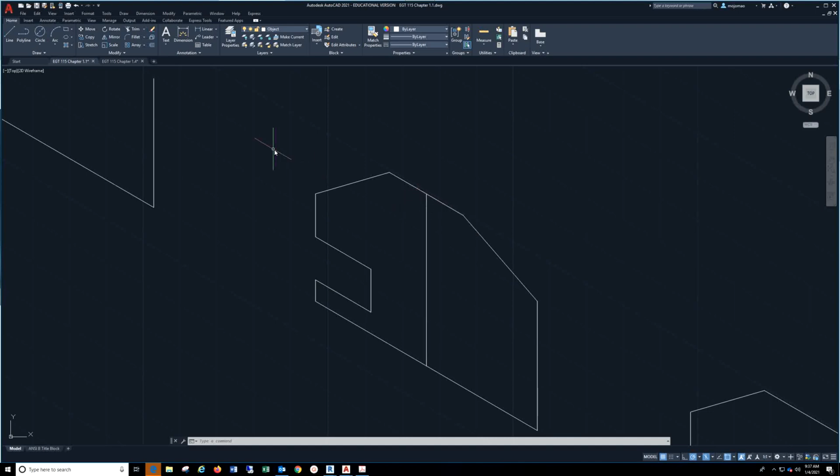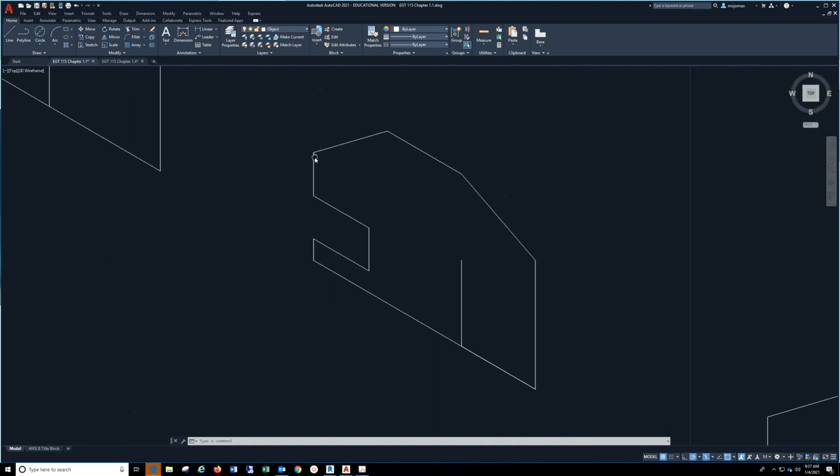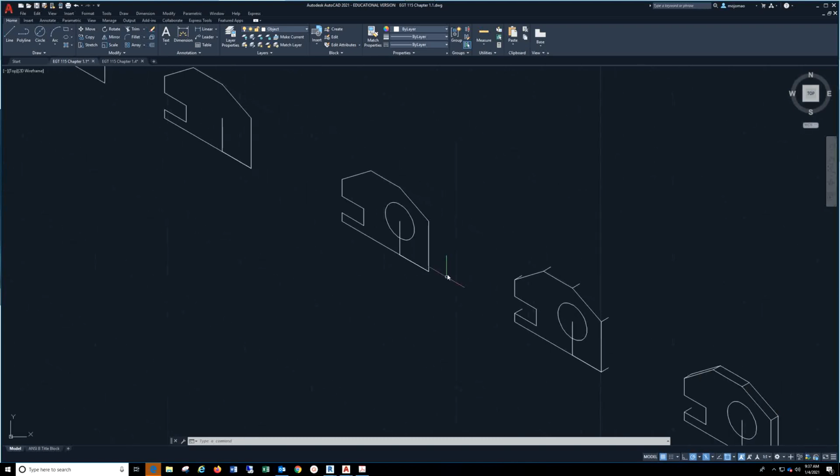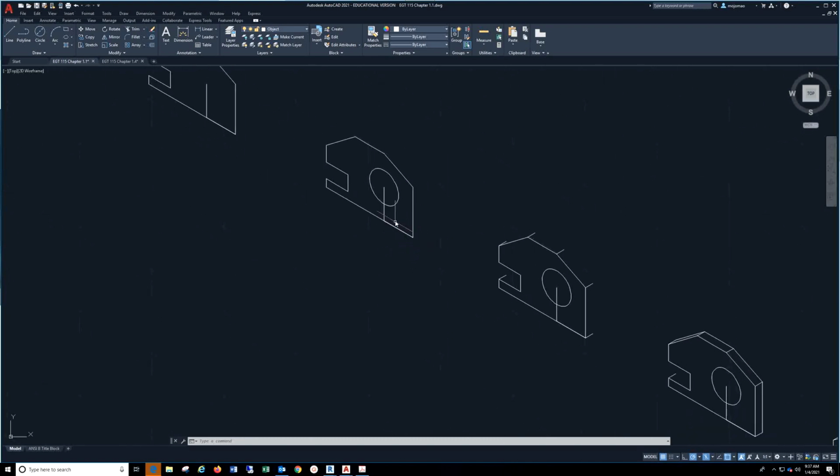So once you have that 2, the flat part at the top is going to be 1. You're going to draw one line at a 1/2 inch, another line at a 1/2 inch, and then all you'll have left to do is connect those 2 points and these 2 points to the end that you've already created. Okay? Now for the circle, you're going to use an offset command of 1. So you would go here, type in 1, select this line, and move it over to here. And then you could also choose the bottom line and offset it up 1 and have a crosshair.